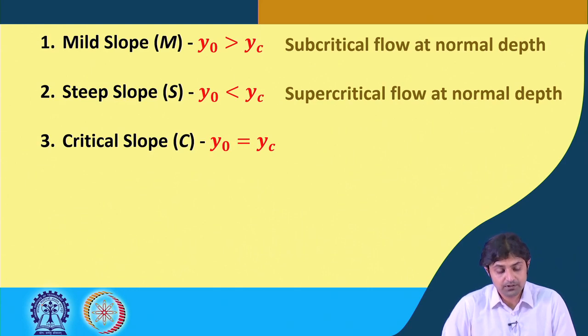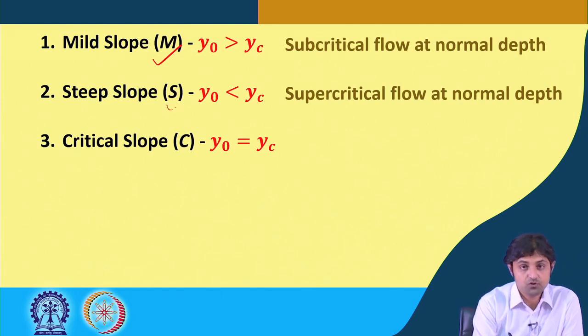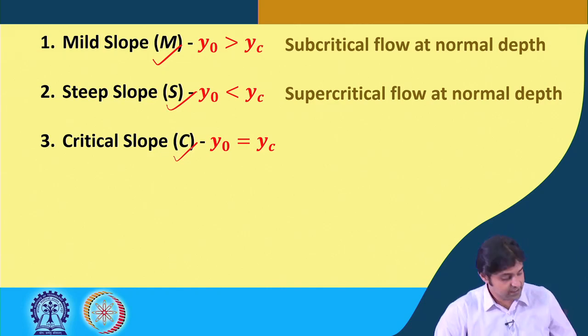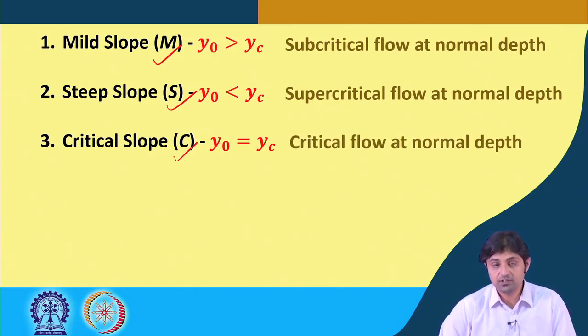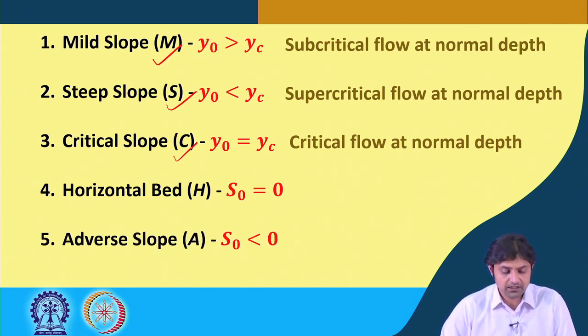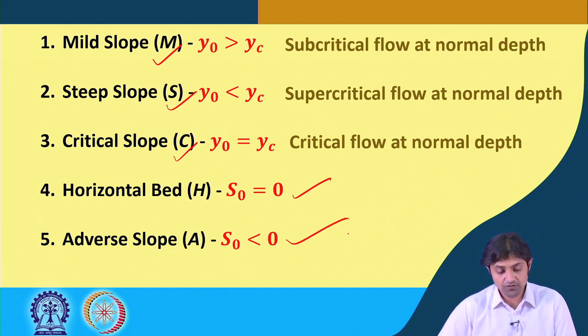At critical slope, this is called the critical slope C. So, mild slope is denoted by M, steep slope is denoted by S, and critical slope is denoted by C. Y naught equal to y c indicates that at normal depth there is a critical flow. The horizontal bed means S naught is equal to 0. That is very simple to understand, right? And in the adverse slope S naught is less than 0. So, using all the conditions before, there could be 5 different types of channels.